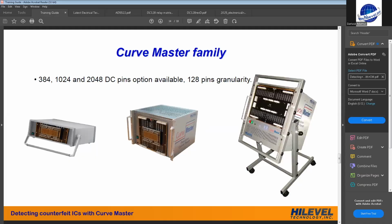And you have 3 different packages available. The small one on the left is up to 384 channels and it's just a desktop solution. You can have either a load board with a dartboard, or a test socket in front. The one in the center is up to 1,000 pins, and it means 8 boards in the system. And the one on the right is a regular chassis, 2,000 pins.